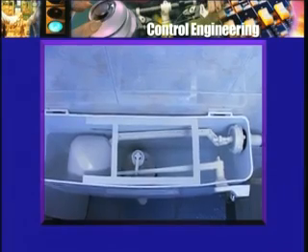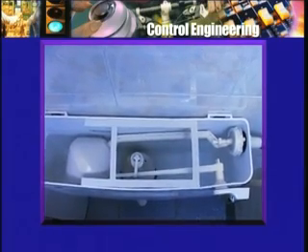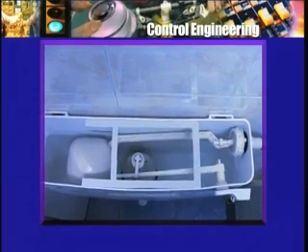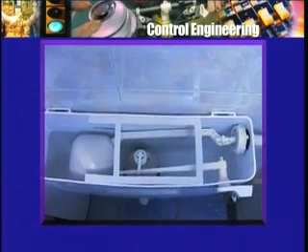So there is an arrangement called a float valve. That is, there is a valve that is controlled by a simple thing that keeps on floating. It's usually a ball, spherical ball or bob of copper, hollow ball of copper connected with a lever to a valve, something as crude as that. Such float devices are quite old.